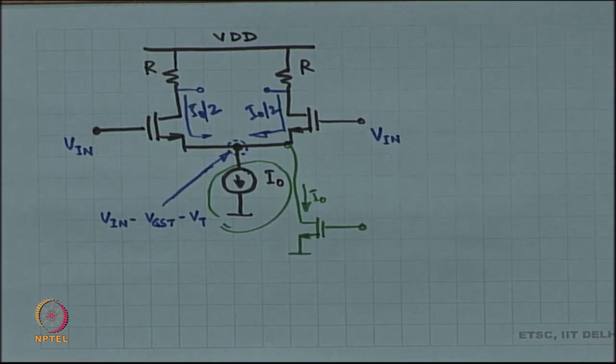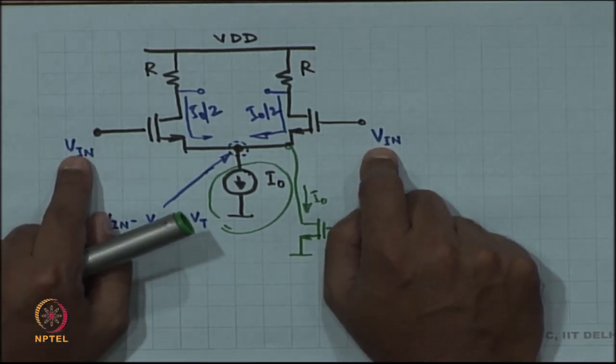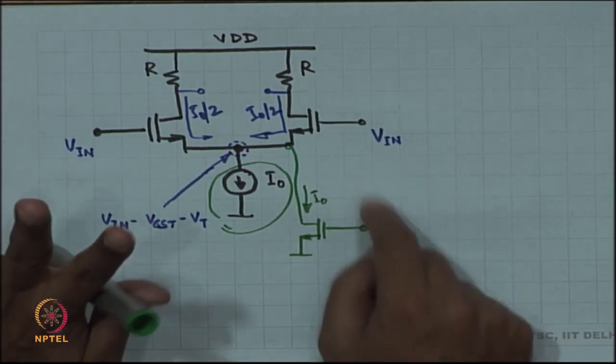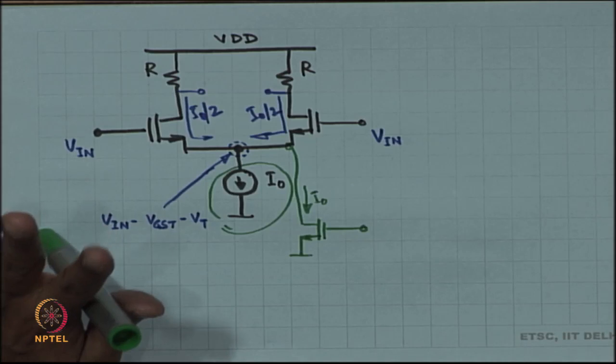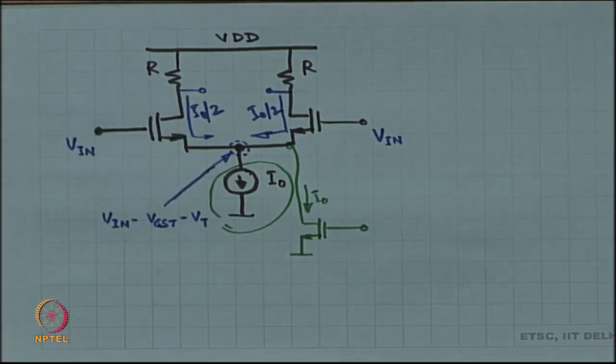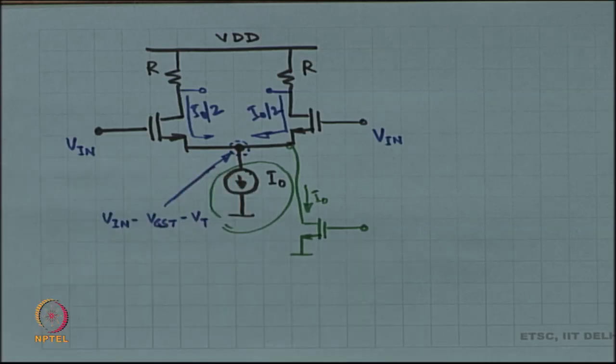All right. Now, let us assume that we have picked the DC operating point value of these two inputs such that this device is indeed in saturation and there is room, you keep some margin, some headroom over here, so that maybe if the signal is larger or smaller, it still remains in saturation.